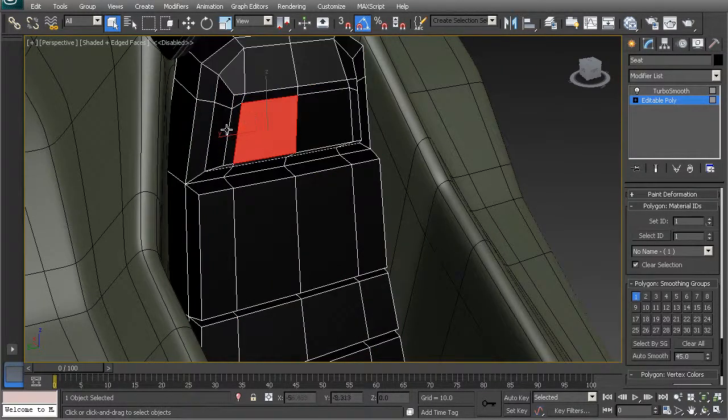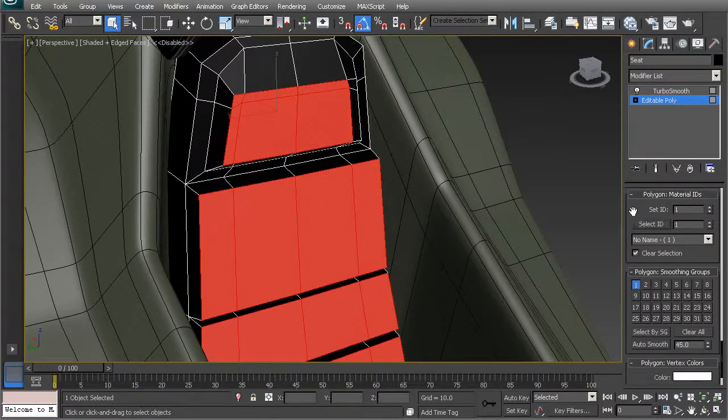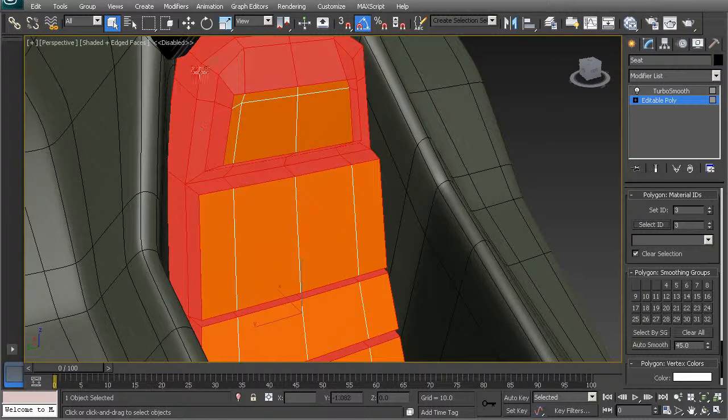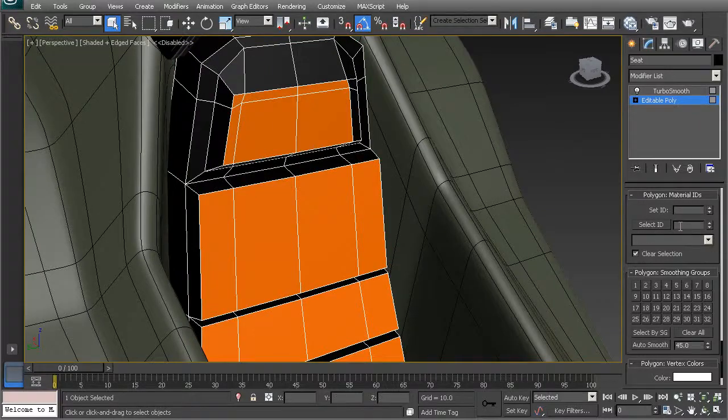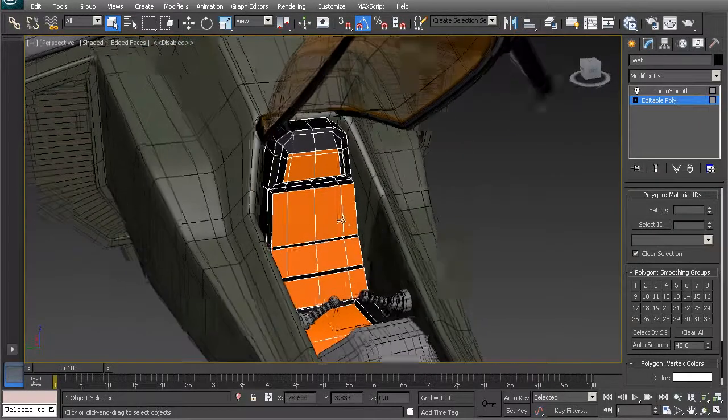Let's select this. Okay, that's been set to 1. So let's select ID. That's all been set there. And let's switch this to 2. There we go. And now I'm going to go up to 3, select ID. That should select all of those outside there. And then we're going to set this to 1. Okay, so we've just used the select ID function to set up our materials properly there if we were to make a mistake.